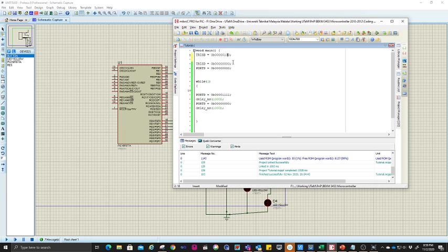This should be 0. This is 0, 1, 2. Okay. For the condition, you just need to put PORTB as 0, because normally for input you do not require an initial condition, but this one you have another output there. So you just put everything as 0, all 8 of them.